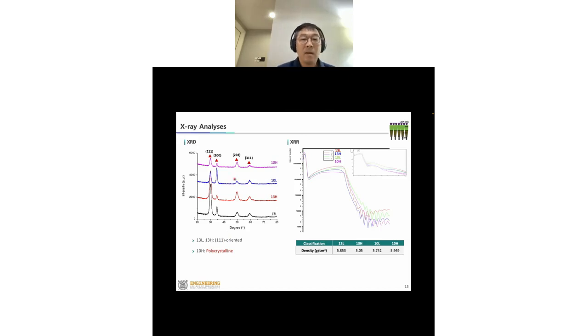That also confirms our XRD observation, that there are some orientations of the crystallinity, and when we have this dense film, it turns out that the dense film has a polycrystalline structure. So it doesn't really have a certain orientation, but it's a well-formed crystalline, and the grains can be grown using certain deposition conditions. So it's a great finding that we can grow our structure into polycrystalline films.